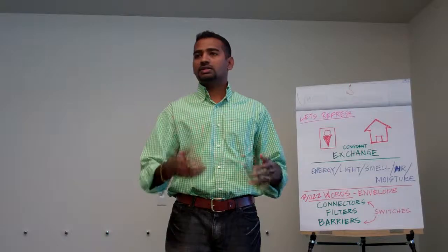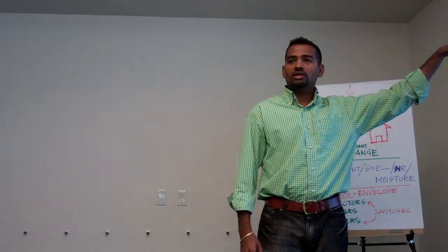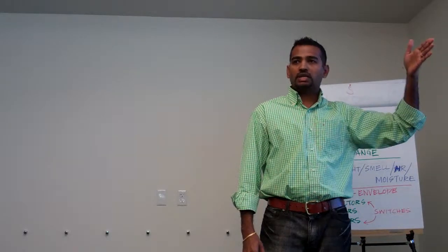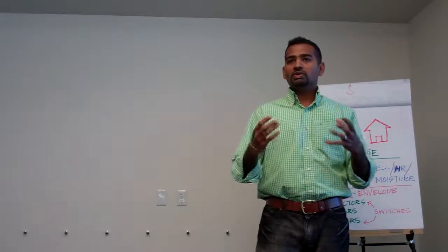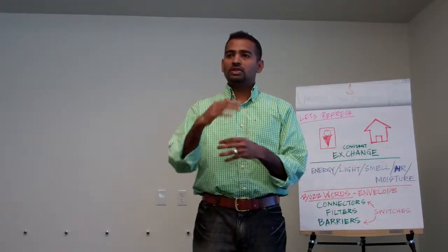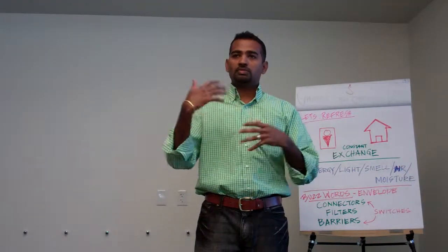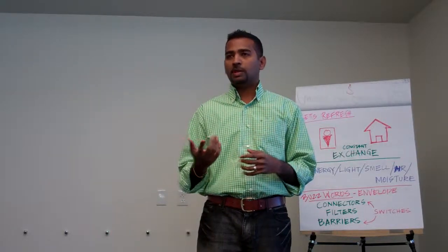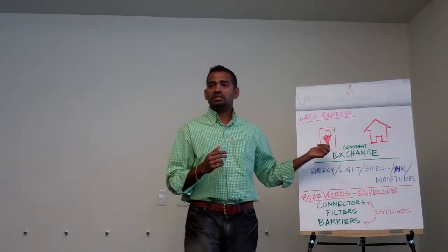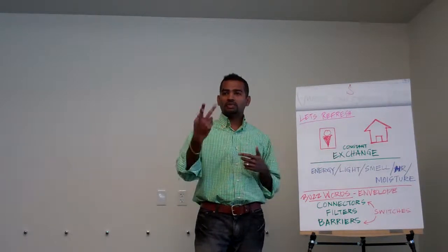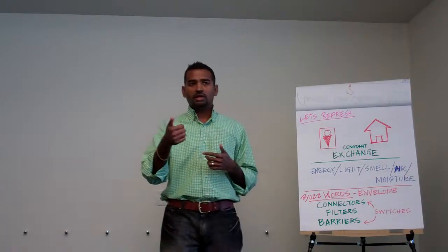The simple answer is an awning. You could have an awning when it's needed, or you could take it down when you don't need it. So you and your project team and your owner are willing to design with those switches so that the building facade changes and the building envelope changes, operable louvers, a higher tech version of it. Right, okay. Thanks for bringing that up.